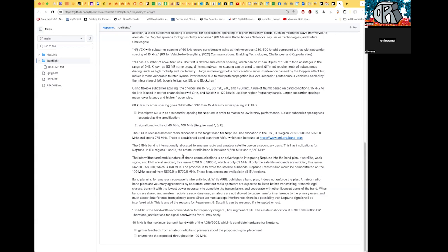So using that sort of knowledge, I think we're really good in the allocations and the bands that they've picked, that up to 100 megahertz isn't going to cause any trouble. And yeah, like you said, the broader the bandwidth, the more resilient the signal is to a lot of different conditions.